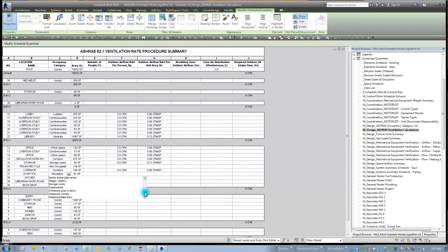So a restroom or toilets public. This toilet space isn't included in ASHRAE for ventilation. It's listed under the exhaust. I've included it in the pull down so that I can assign it to my space and show that it's got 0 CFM ventilation required. The kitchen space, that's basically a break room. So we'll choose a break room there.